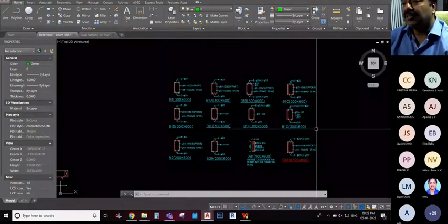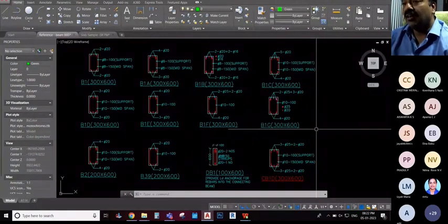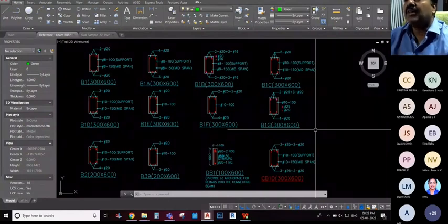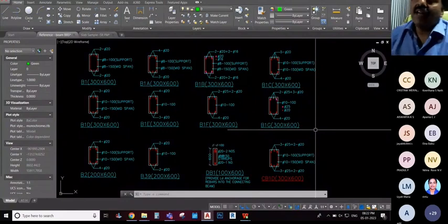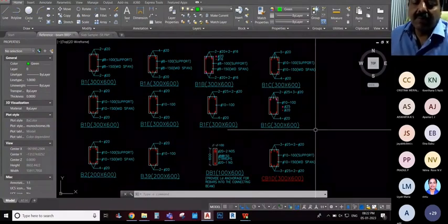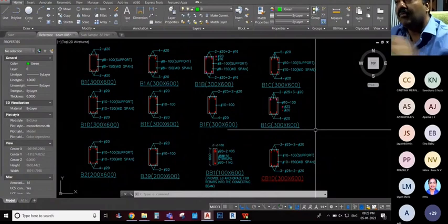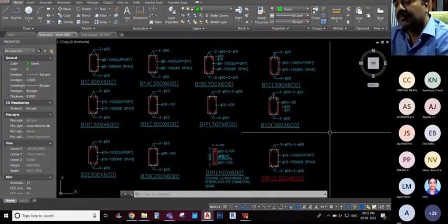But the problem is there will not be quality. In the longitudinal section, it will not say where to cut the bars, where to lap the bars, etc. So there are things like, you cannot lap the bars at the bottom of the beam in the midspan.